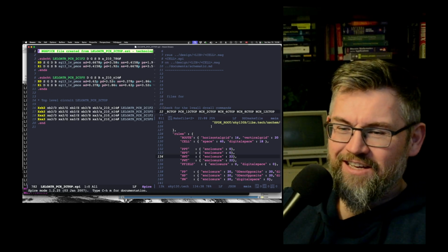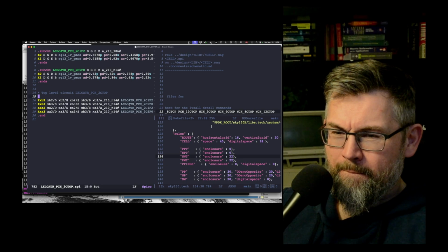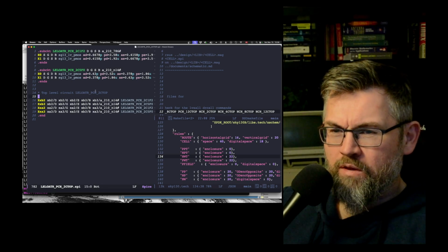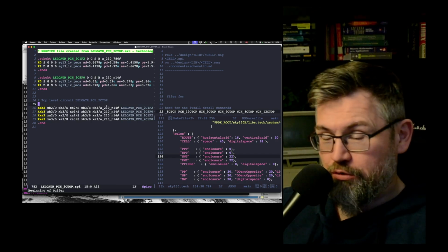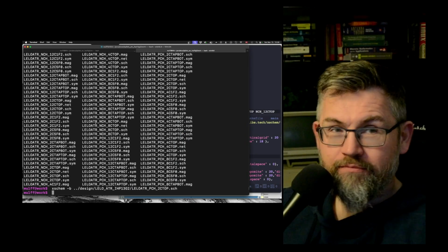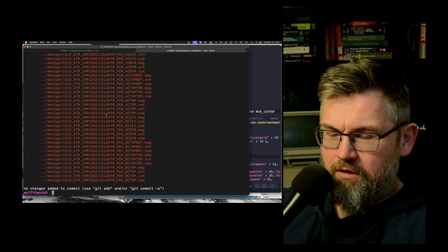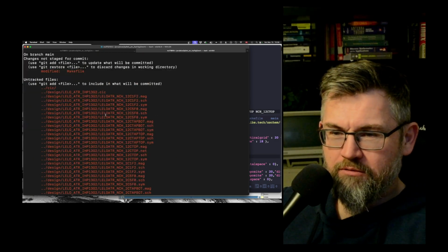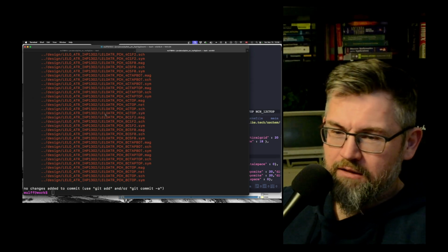So Magic apparently doesn't write the netlist if you don't have any pins. Who knew? Okay, doesn't really matter. The library is complete. I have all my transistors now. It is DRC, and at least the transistors are LVS clean.